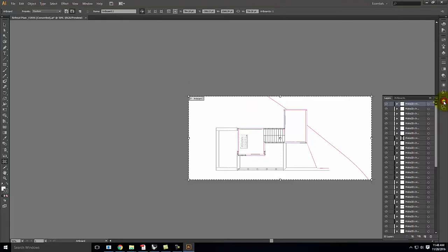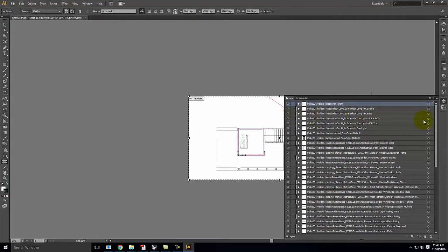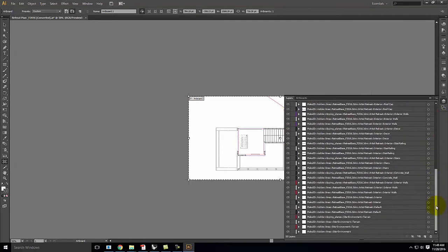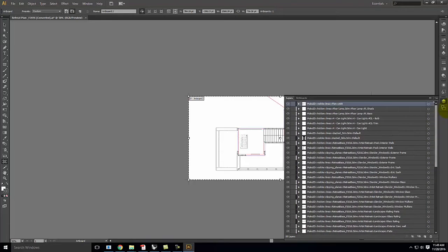And like I said, this time I chose to maintain the source layers. And so I cautioned you about doing it because rather than having 2 layers, we have a bunch of layers. Okay? The advantage here is that if I wanted specific things to be certain line weights, say, my walls to be thicker than my windows or something like that, because they're divided up, it makes it easy.